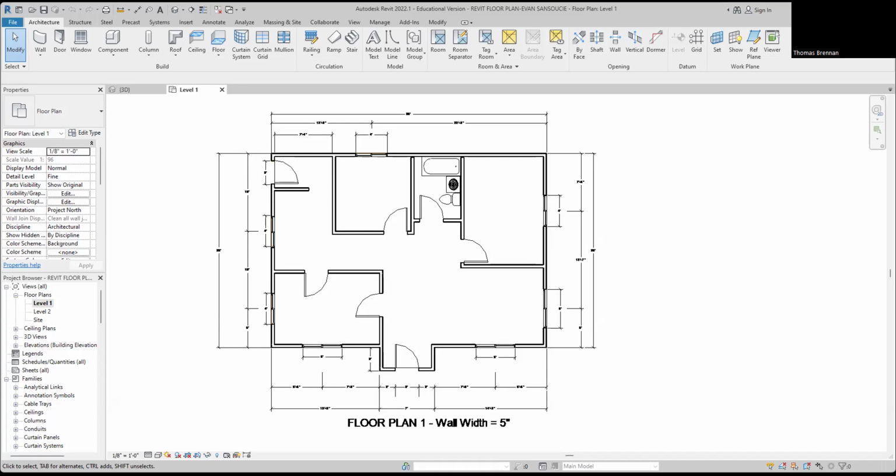Yeah, so you basically are going to take, we're doing this 10'8". So what you want to do is you want to pull this down until you see the 10. Okay, so you get the 10 right there. And then what you do is you get that on there and then you count these little inches. Okay. Would I start from this side? You're going to start from this side. 0 and then over this way. And you should be able to count up to 8. Yeah. Yep, got it? Okay. Does that make sense there, Ethan? Okay. Yeah, go ahead. We'll give it a shot, just to make sure that you feel good about that.